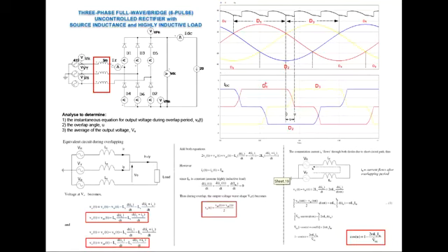However, the current through D1 will reduce at a certain rate from IDC to 0, and we also see that the current through the yellow phase will rise from 0 to IDC at a certain rate. There is an overlap of current during this transition.